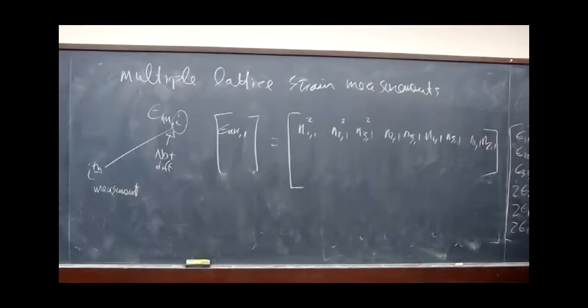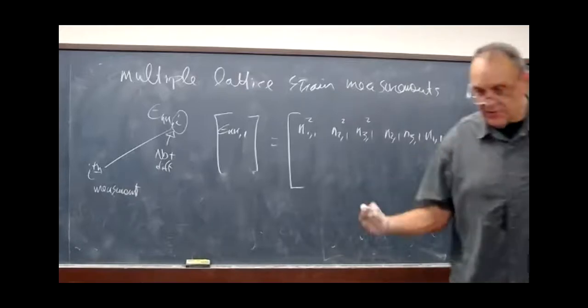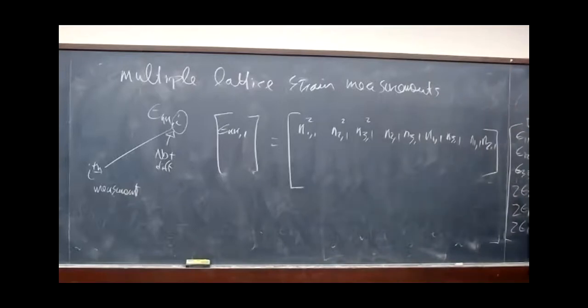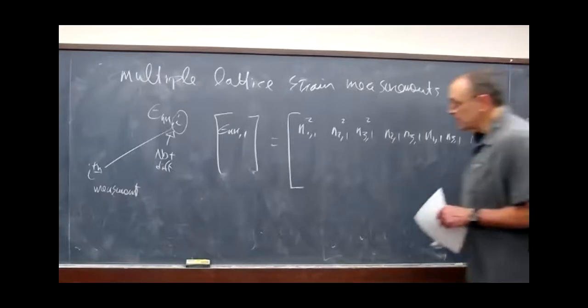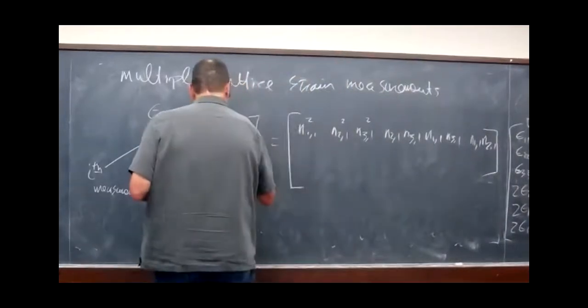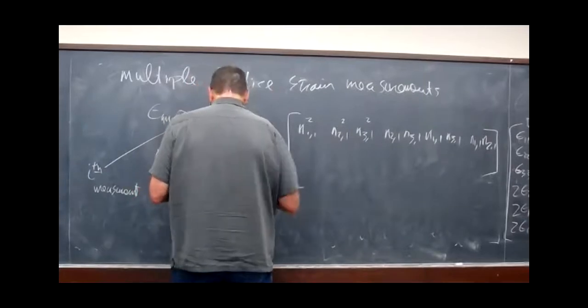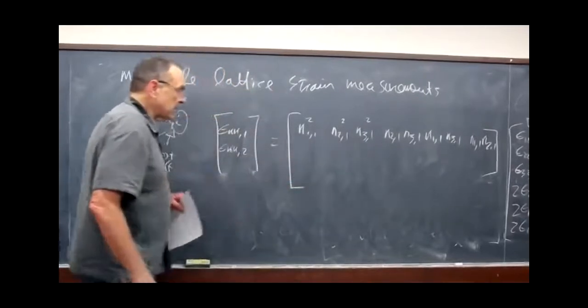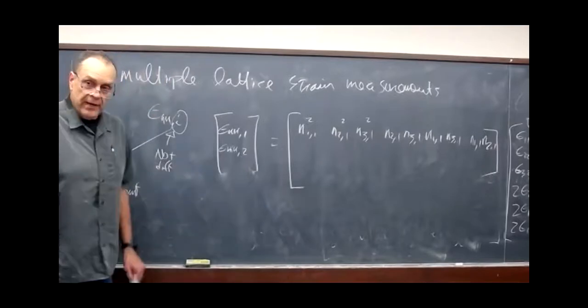When we talk about elasticity in a little while, we're going to do this again, and this is a typical ordering for when I take the strain tensor and turn it into a vector. You do the normals, then you go 23, 13, 12, and you put a 2 in there. That takes care of the fact that there are 2 shear strains. Then I just keep going, right? So now I have n 2, and you just have a system of equations.